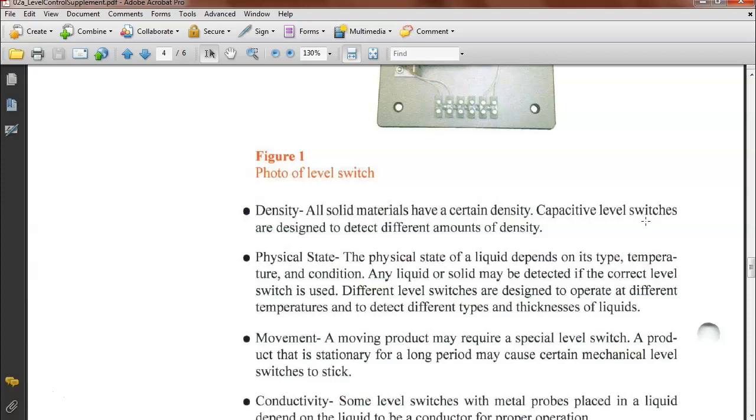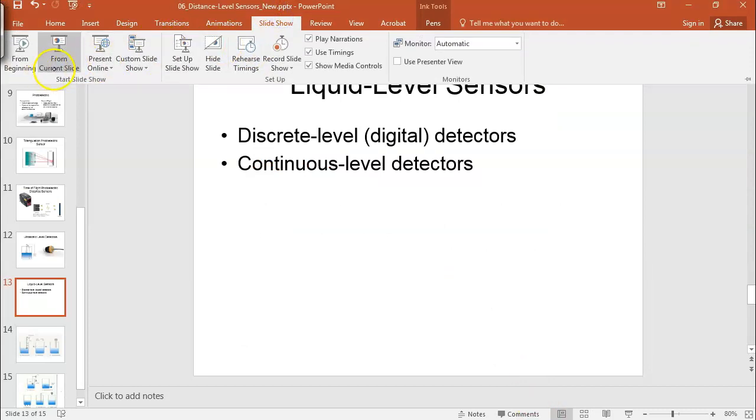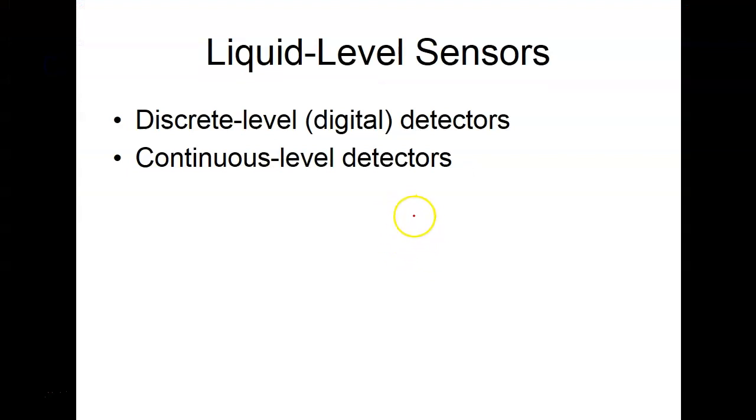used a resistive element. What determines the resistance of a conductor? Distance it travels, right? First, we'll start off with the material it's made out of, and then the physical size of it, right? And the distance. What's the fourth thing? Yeah, temperature.